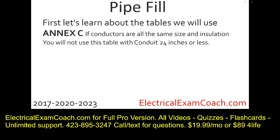You will not use this table if the conduit is 24 inches or less. Now, the code book uses the term nipples, but I want you to imagine in your mind, anytime the conduit is 24 inches or less, you're not going to use Annex C. You're going to use the method that I'll teach you in Lesson 7.2. You can head to page 712 of the 2017 and page 729 of the 2020. This video is 2023 compatible. You'll have to get to your page number for Annex C, and then you can follow along.